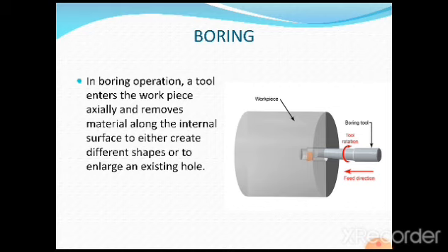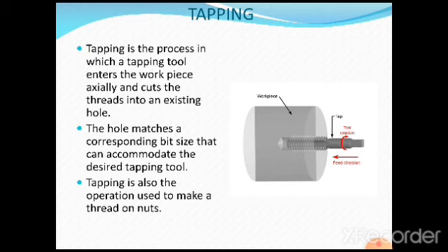To create different shapes means what? Different internal steps cutting can also be done, or even to enlarge the existing hole which was previously made by the drilling operation. Such an operation we call a boring operation. So remember, boring operation is nothing but production of a slightly larger hole than the drilled hole. That is the main point. And we are coming to the last concept, that is called tapping.